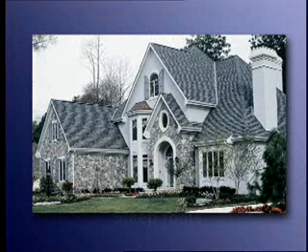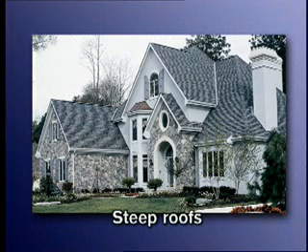Steep roofs have slopes higher than 3 in 12 pitches and have a large variety of shapes. Steep roofs are more expensive to construct than flat roofs, but shed water more effectively. Its finishes are more varied because the roofing material can include small overlapping individual units. The drafter should be aware of the terminology for the different types of steep roofs.